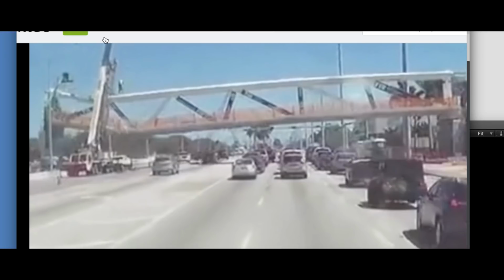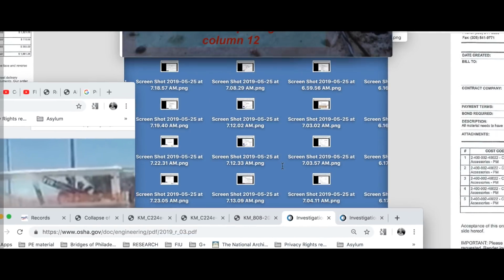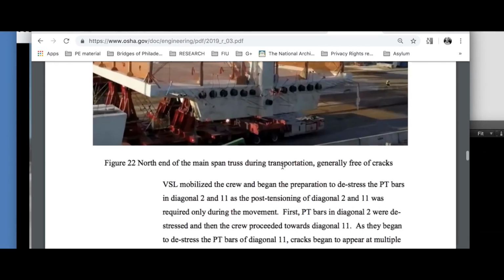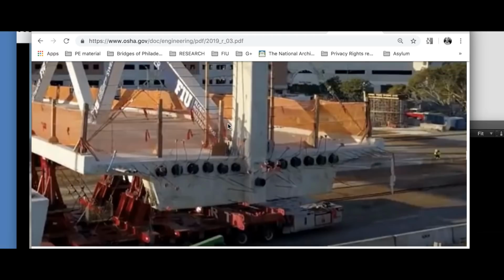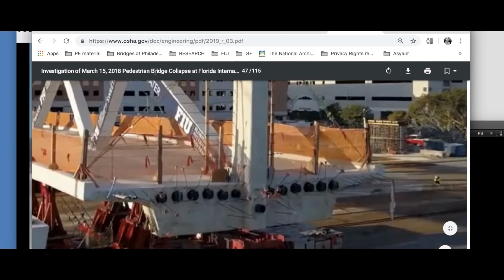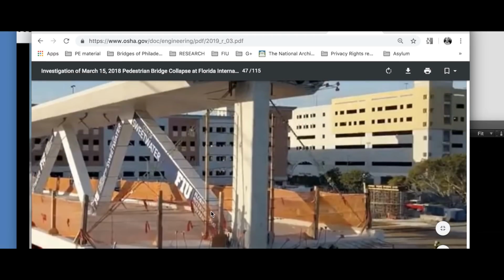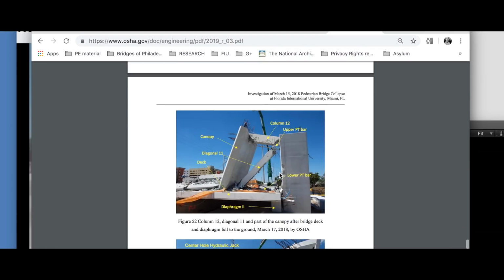And that would look something like, bear with me, so there's that nodal point I was talking about with you, right here. This is the 12 inside here, right here. It's already deteriorated. Number 11 is at the bottom, but with that much deflection we see in the image, number 11 is now torn up through the top of here, because 11's gone down through the post-tension rod.